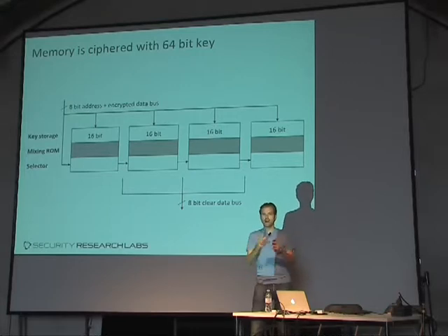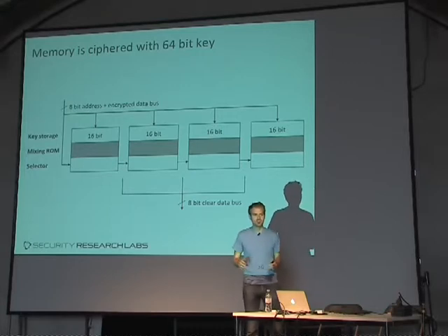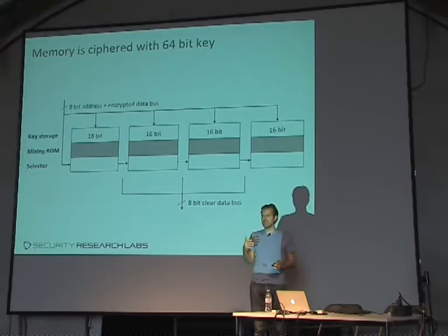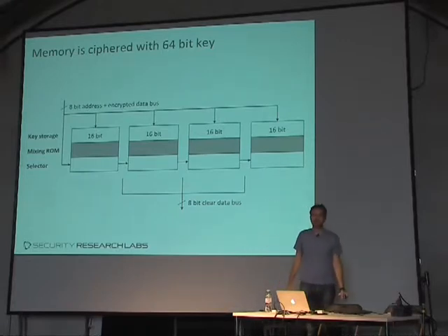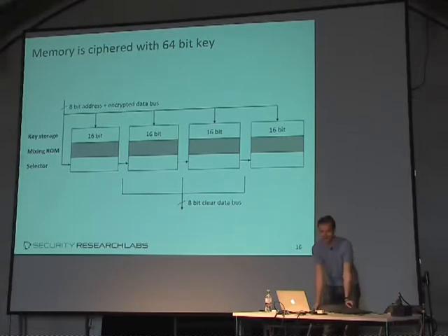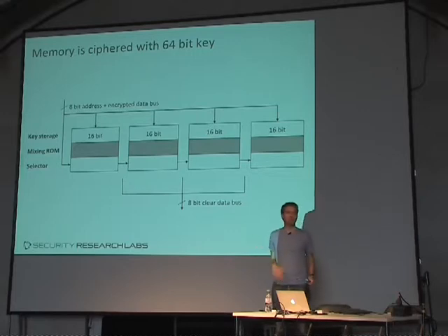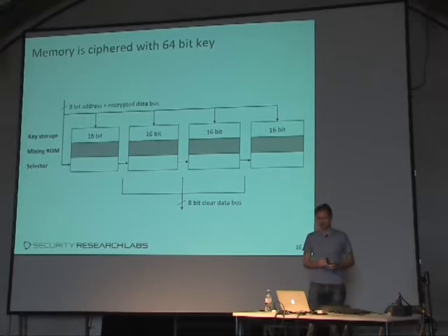It's kind of an on-wire encryption, and it has to execute a full block cipher cycle in half a clock cycle, right? DES is implemented on this smart card, and that's probably the most hardware-optimized block cipher I can think of, at least of the standard ones, and that takes 16 clock cycles on this chip. So they try to create a block cipher here that's something like 30 times faster than DES, while providing some reasonable level of security. And of course, that latter part didn't work out so much.